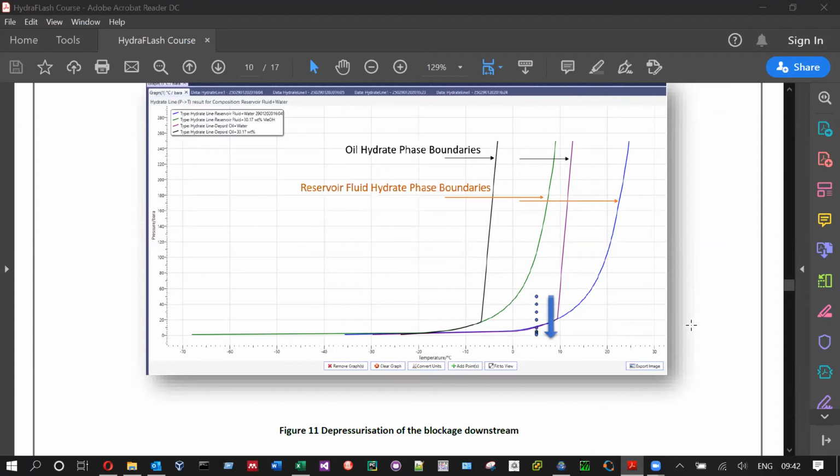For example, if you have a pipeline with an injection point and your pump in location 1, and you want to know the differences in the dissociation point through the pipeline, because the methanol is injected and you have this gradient of concentration of methanol inside the pipeline, you need to enter point by point the concentration of methanol in each section of the pipeline.